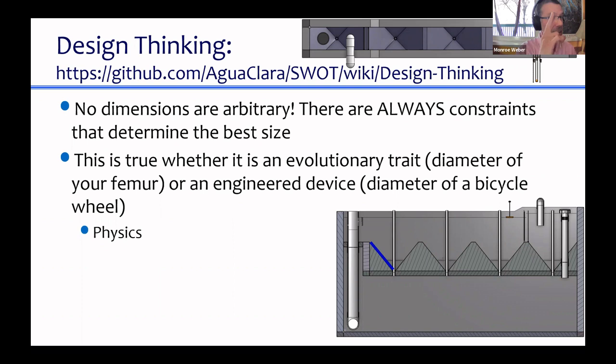And then the other thing is, you would like a plant operator to be able to grab hold of the top of this pipe, pull it out, let the thing flush, and then put the pipe back in again. That means that the pipe should be human length. It shouldn't be really, really long, or it's going to be hard to get it back into the hole again. So that's another constraint.